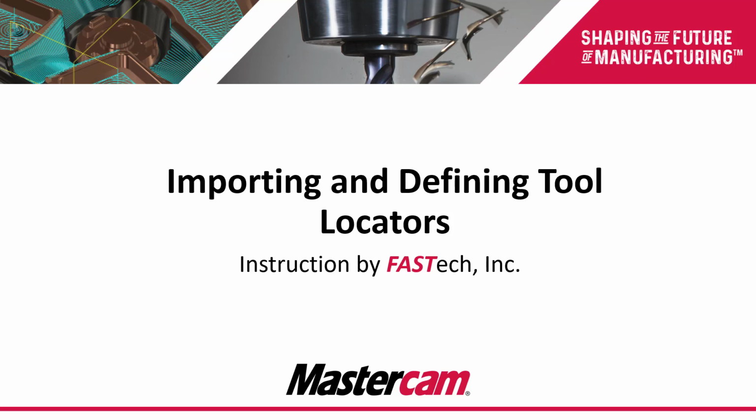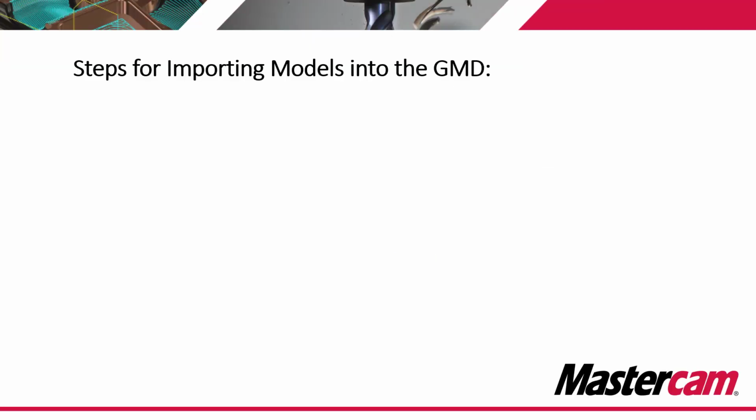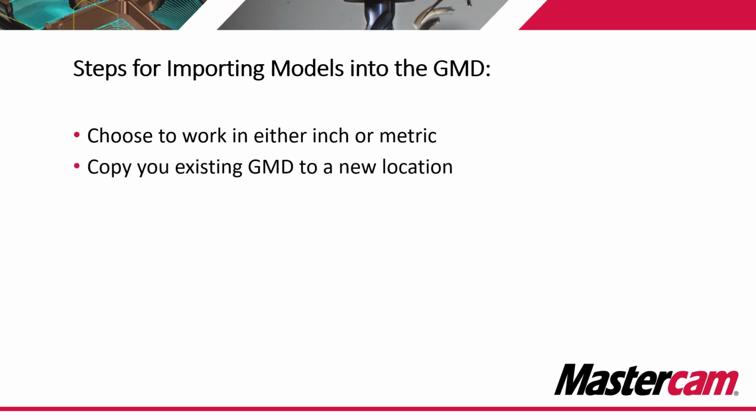Welcome back to this third video in the series on Mastercam Mill-Turn Tool Locators. In this video, we're going to take a look at importing the models and then starting to define the tool locators. To start, we need to just figure out whether we want to work in inch or metric. We can choose either one, but we'll want to select the appropriate GMD to start with.